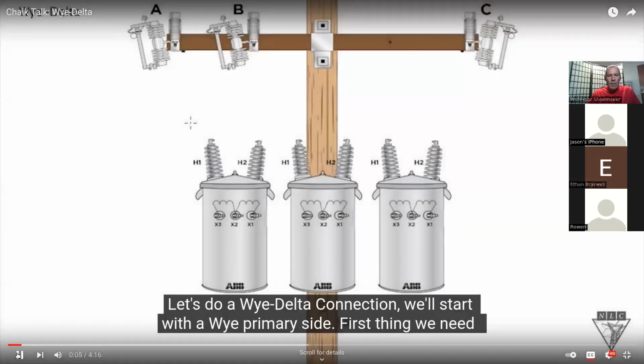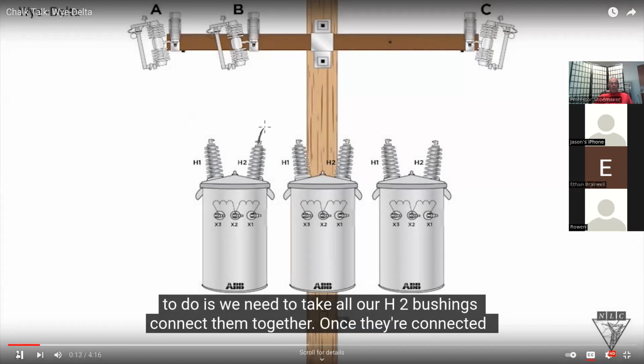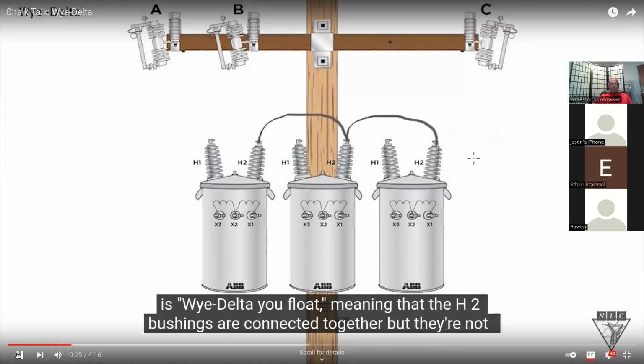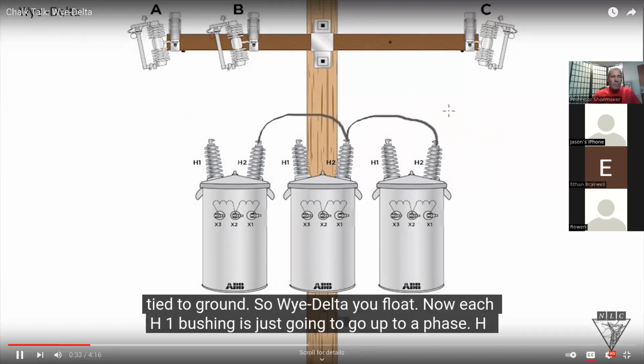Okay, so let's do a Y delta connection. We'll start with the Y primary side. So first thing we need to do is take all our H2 bushings and connect them together. Once they're connected together, we're not going to tie it to ground. So a common saying with a Y delta connection is Y delta you float, meaning that the H2 bushings are connected together, but they're not tied to ground. Once again, that's the reason why we call that a floating neutral. It's not connected to the system neutral.